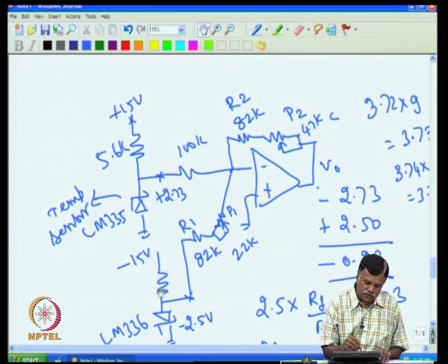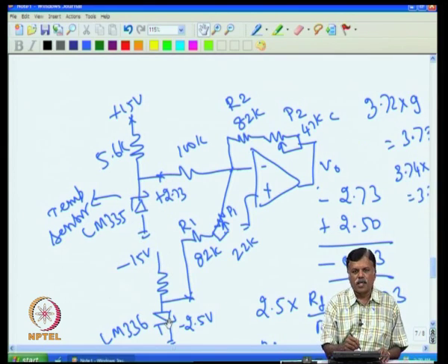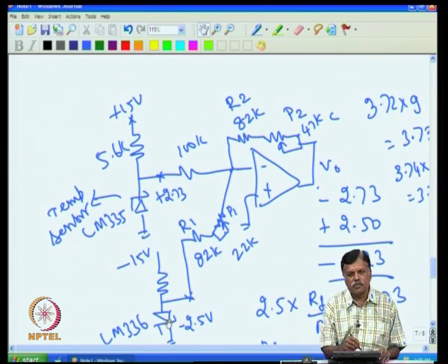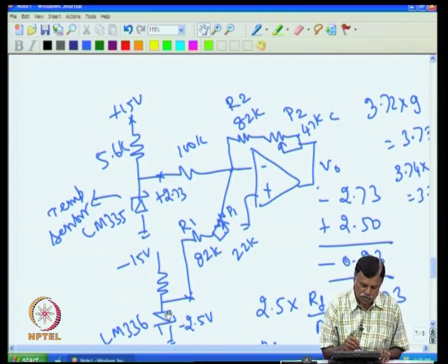So, you have 12.5 volt across this, and here also it needs 1 milliampere current through this, and some small current is flowing through this. Even if I neglect that, if I want to keep the same 2 milliampere current like what we have done here, 2 milliampere through this, because this also works well from 1 milliampere to 10 milliampere. So, if I want 2 milliampere current to flow through this, then 12.5 volt is across this.